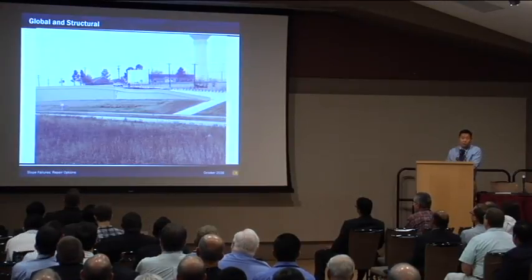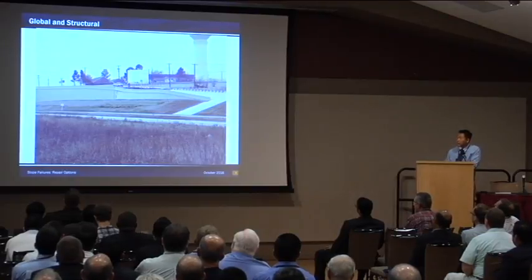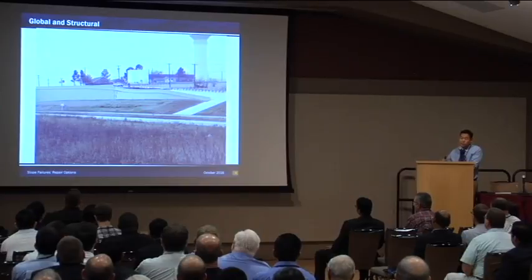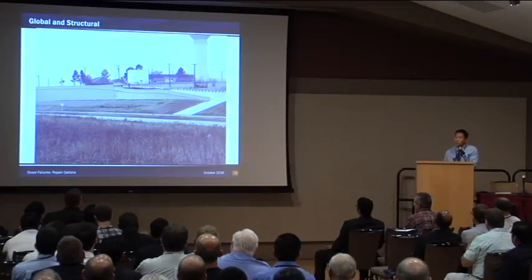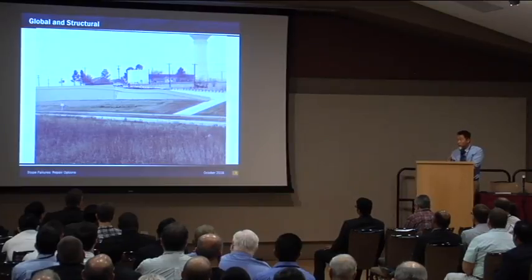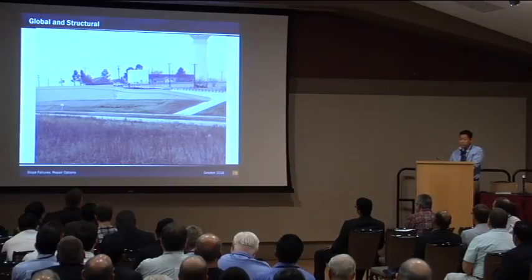This was a slope failure in North Texas, and a retaining wall built on an embankment consisting of clay. It has a special history, at least the job site has a special history. At the location where the slope failure occurred, there was a previous drainage ditch or drainage creek. In most cases, if you see a drainage ditch or creek, there is a soft deposit due to alluvial deposit carried by the water. So if you see an existing pond, creek, or drainage ditch, you should make sure you remove all the soft material and replace it with a better material.